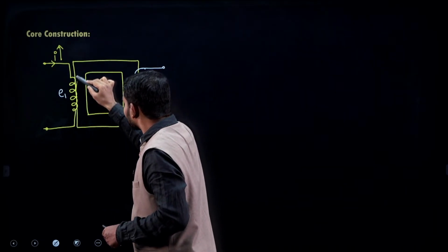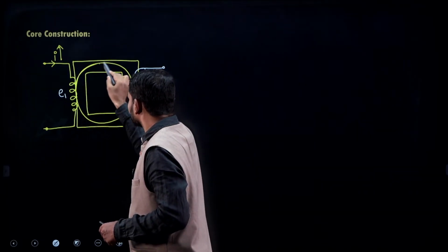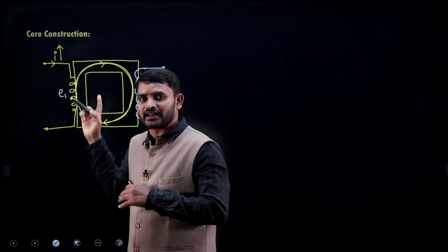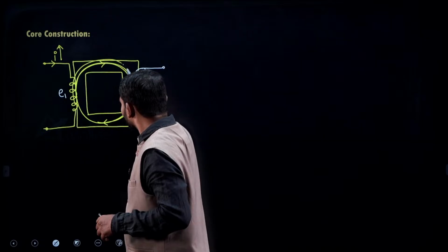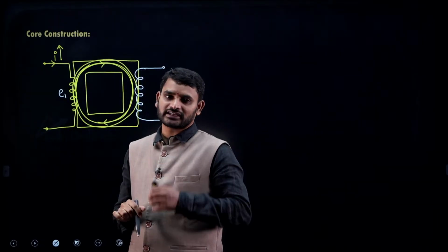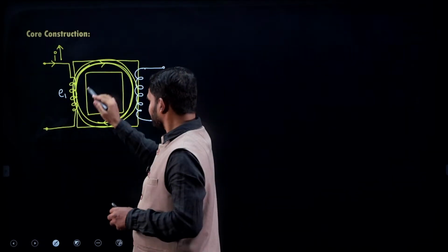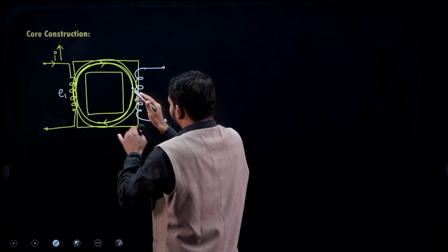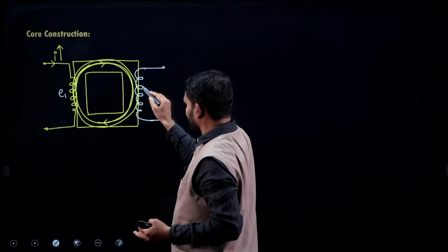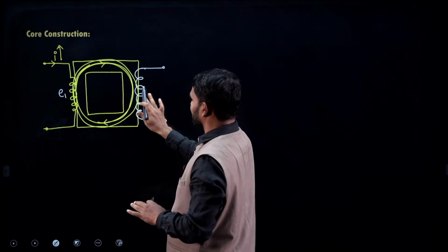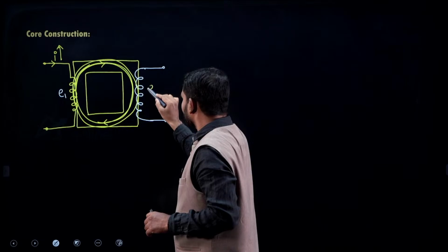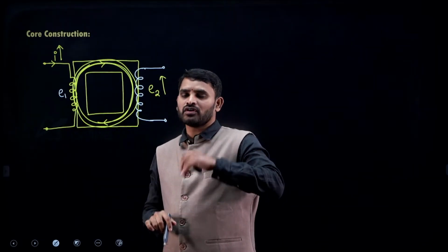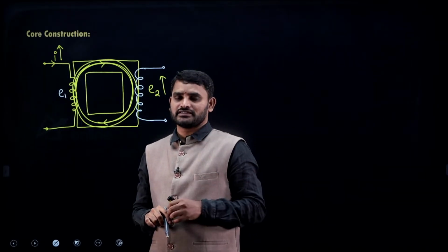Now, the flux lines try to establish through this low reluctance magnetic path. Earlier some flux lines were establishing on the left side and right side. Now, most of the flux lines will be establishing through the low reluctance path. Because of this, maximum flux lines are diverted into the core, and therefore, when you place the second winding or other coil on this side, most of the flux lines will be linking with this winding, and hence the induced EMF in this winding will be more. Earlier only a few flux linkages, now more flux linkages, and hence the EMF increases.